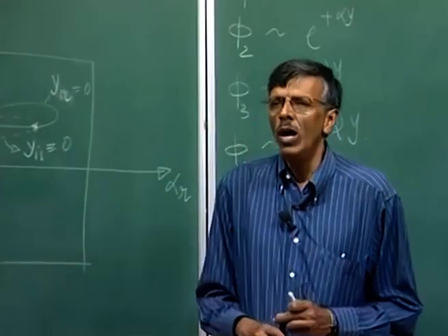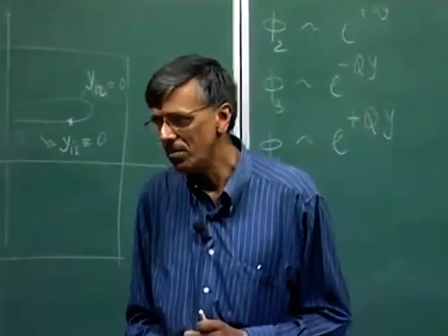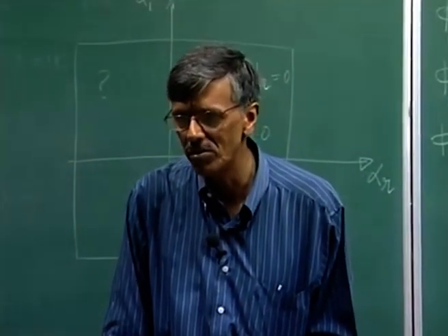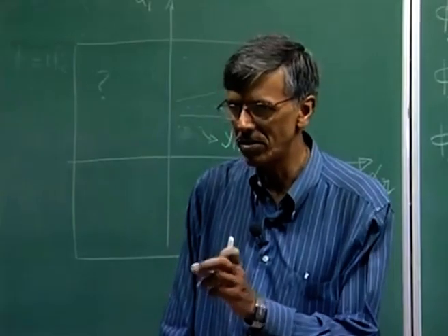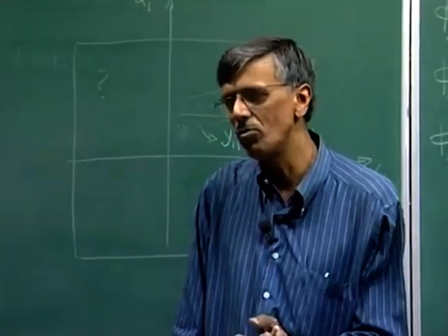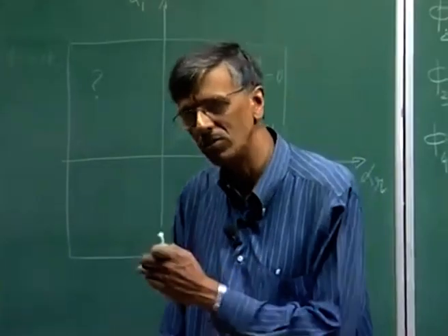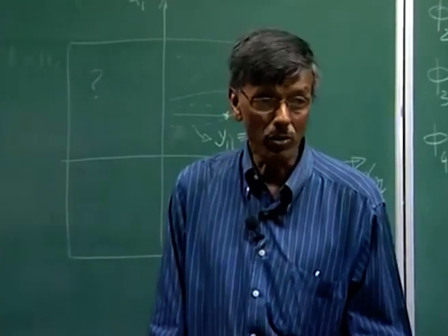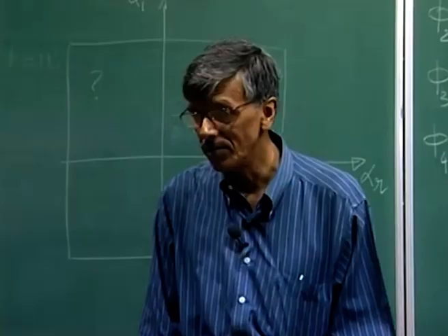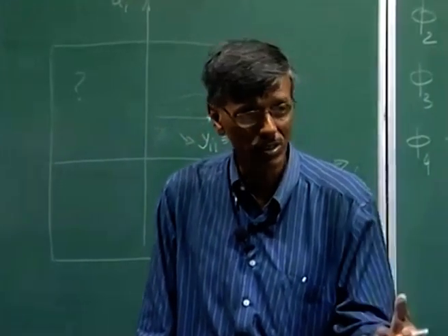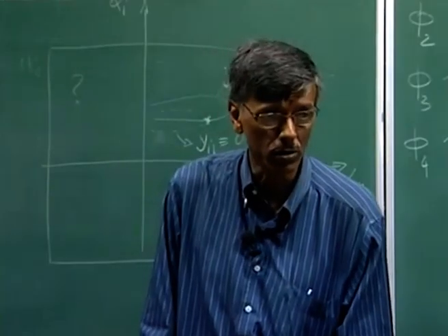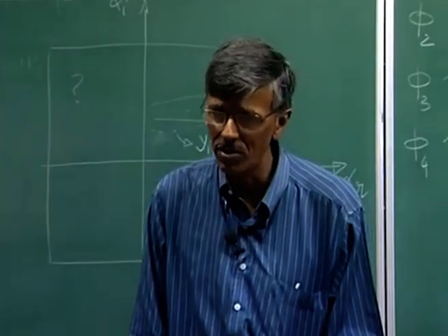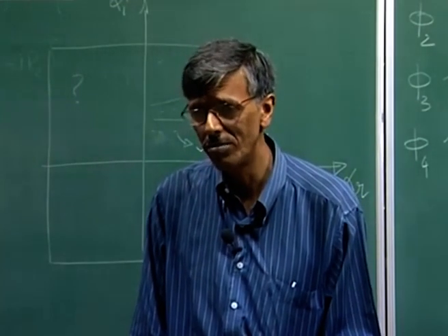Okay. As far as the phase is concerned, if my omega remains the same and alpha has become negative from positive, what happens to the phase? Phase speed is going to flip sign. So, in one case, if the phase was traveling to the right, in the other case it will be traveling to the left. You can do the same exercise with the group velocity, which will not necessarily be concomitant with the phase speed. You will have to work it out. We did work it out, and we found that some of these eigenvalues on the left half plane also travel upstream.